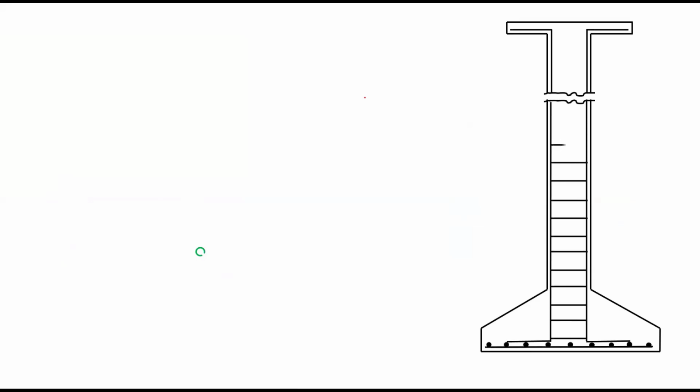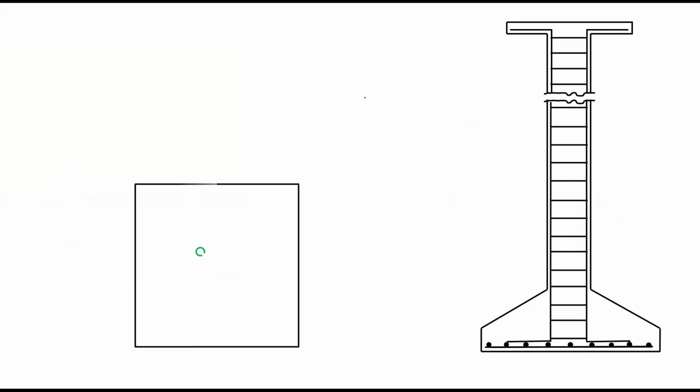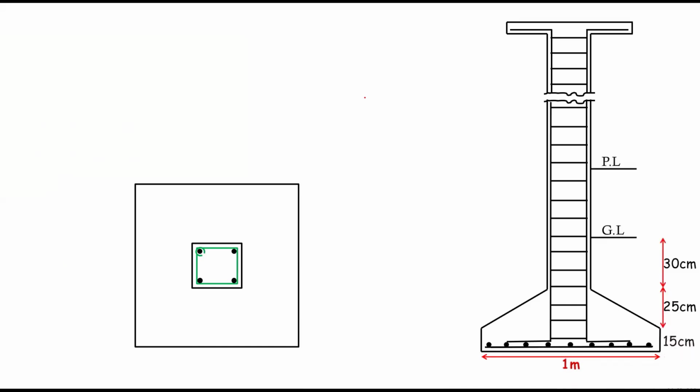You can see, okay, main bars, there are ties, okay. Now, ties are just the same thing as stirrups, but this terminology is just used for the rings which are being used in column, okay. And stirrup terminology is used for the rings which are being used only in beams, okay. So never be confused with the tie and then stirrup.